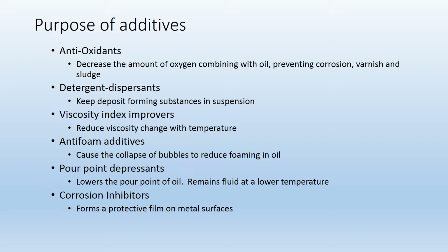Anti-foam additives cause the collapse of bubbles to reduce foaming in oil. Pour point depressants lower the pour point of the oil and remain fluid at a lower temperature. Corrosion inhibitors form a protective film on metal surfaces.